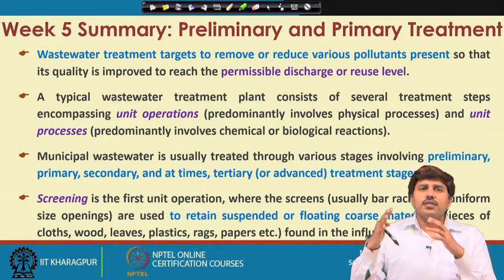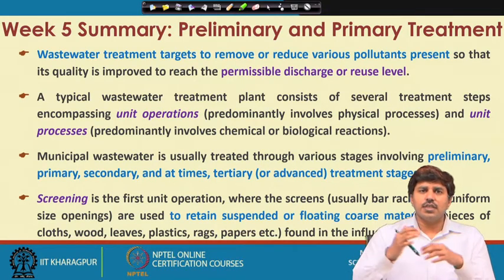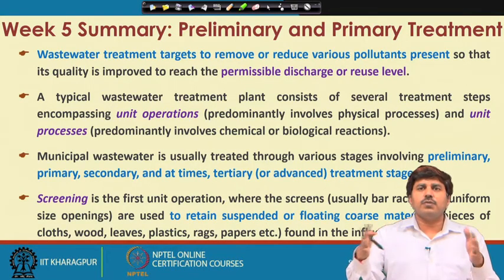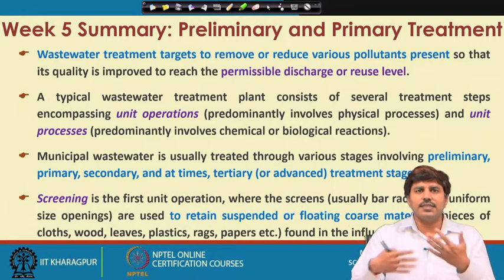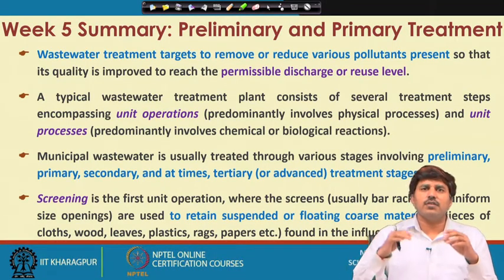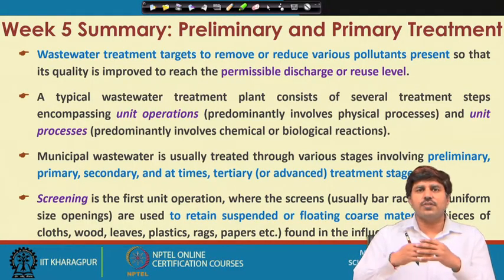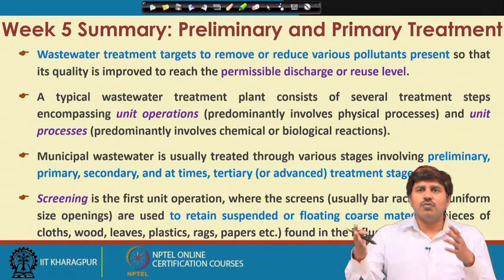Screening is usually the first unit operation under the category of preliminary treatment. Few people combine preliminary and primary as just primary, in which case we can call screening a primary treatment, but usually it is a preliminary treatment, because it is the first stage of treatment, where the screens are usually bar racks.